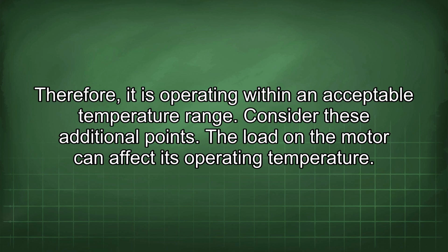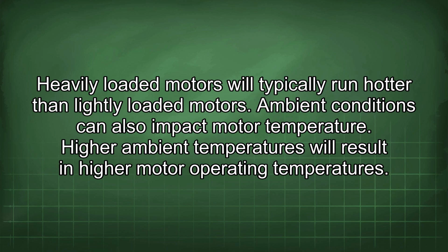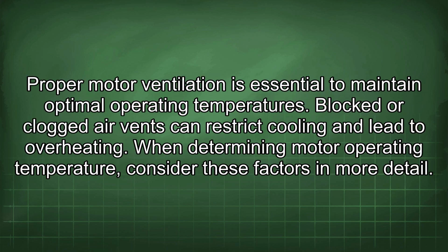Consider these additional points. The load in the motor can affect its operating temperature. Heavily loaded motors will typically run hotter than lightly loaded motors. Ambient conditions can also impact motor temperature. High ambient temperatures will result in higher motor operating temperatures. Proper motor ventilation is essential to maintain optimal operating temperatures. Blocked or clogged air vents can restrict cooling and lead to overheating.